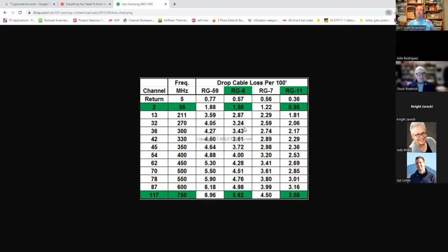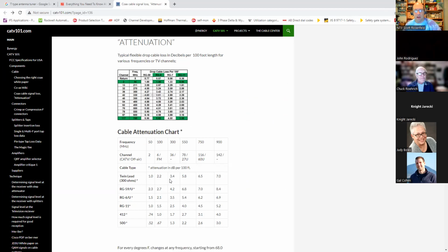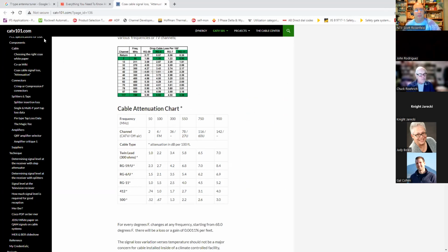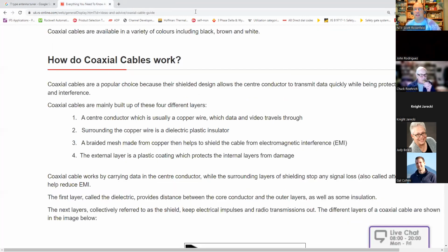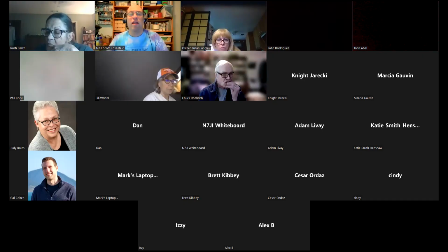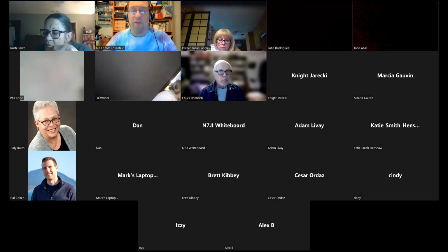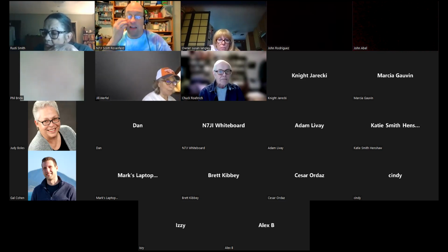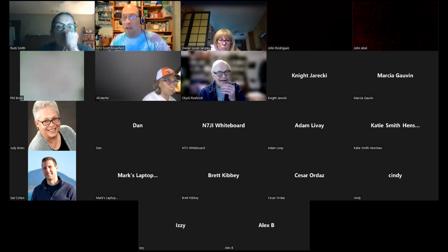And even within, for instance, RG, notice that there's lots of different ones. There's RG59, RG6, RG7, RG11. The most common one that we use is known as RG58. The reason we use RG58 is because it's 50 ohms. And it's also, for instance, if you get a mobile antenna and you stick it on your roof, you can slam it in your door, and it still allows the door to seal, and it doesn't destroy the cable. Now, if we were to use, for instance, RG8,